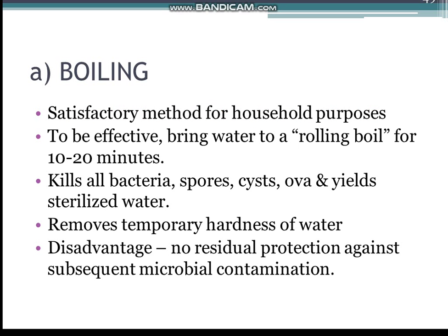First, boiling. Boiling is a satisfactory method of purifying water for household purposes. To be effective, the water must be brought to a rolling boil for 10 to 20 minutes. It kills all bacteria, spores, cysts and ova and yields sterilized water. Boiling also removes temporary hardness by driving off carbon dioxide and precipitating the calcium carbonate. The taste of water is altered, but this is harmless.